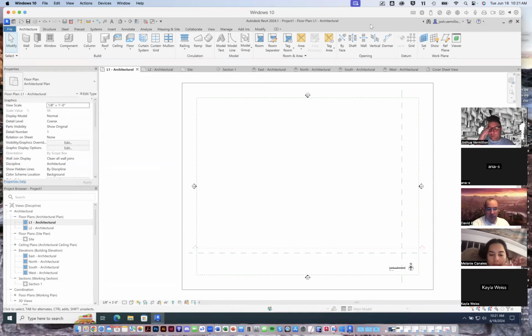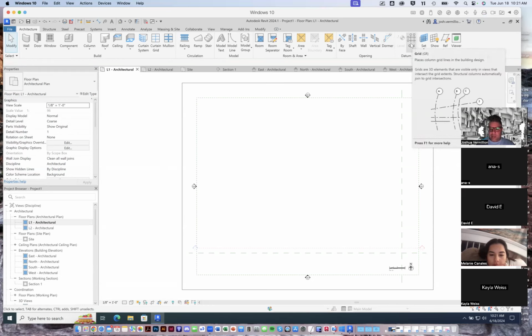So if I think about 144, that's divisible by 12, it's divisible by 24. In fact, if we divide 144 by 24, we get 6. Let's say we have 6 modules of 24 feet. Then that actually could work well with just about any structural system, right? So spanning between columns, 24 feet each, that's an easy span to do.